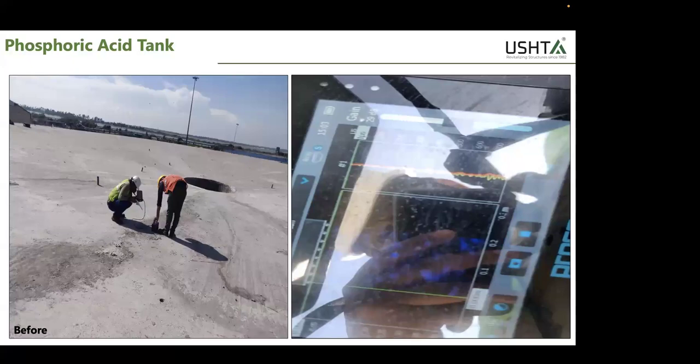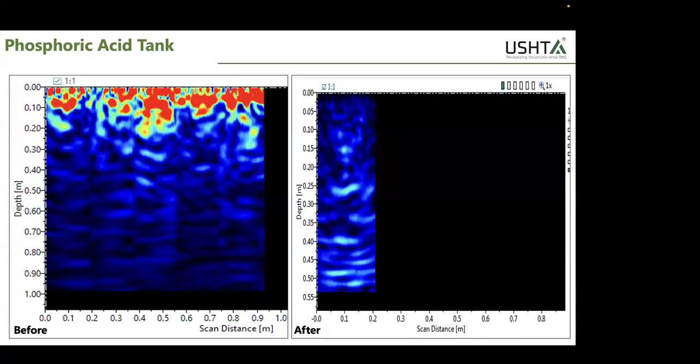All right, proceed. This test you are doing is a UPV test? No, it's not UPV. It's a tomography test, sir. UPV is ultrasonic pulse velocity, and tomography is a much more advanced version of that. What do you do in that? If you can kindly educate me. Tomography is a multi-array system.